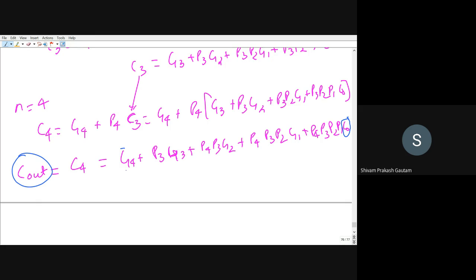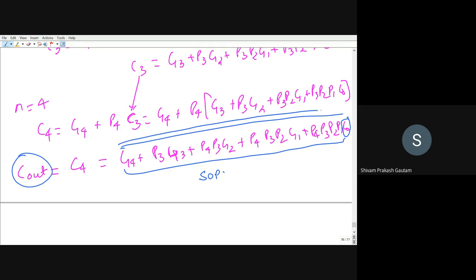And if you see, this logic is currently in SOP form, that is sum of product form. So you can implement it using NAND gate, that is a universal gate. And how to implement it? You can double bar this, right? So you know how you can implement it. Now you can reduce this expression.